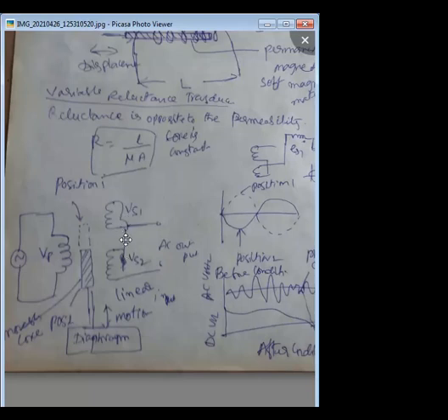But here we will connect them in series opposition. Due to that, the two generated voltages, E1 at secondary 1 and E2 at secondary 2, will be subtracted. Due to that, any non-linearity effects present in the coils will be cancelled out, and we will get the linearized output.